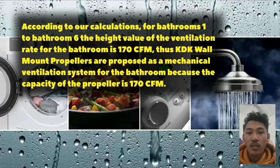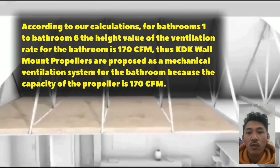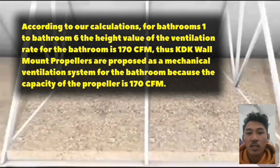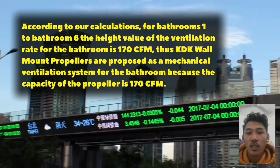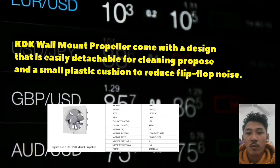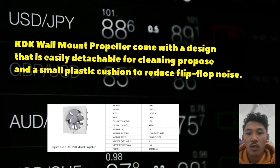According to our calculation, for bathroom 1 to bathroom 6, the highest ventilation rate is 170 CFM. Thus, the KDK wall mount propeller is proposed as the mechanical ventilation system for all bathrooms because its capacity is 170 CFM. It comes with a design that is easily detachable for cleaning and has a small plastic cushion to reduce flip-flop noise.